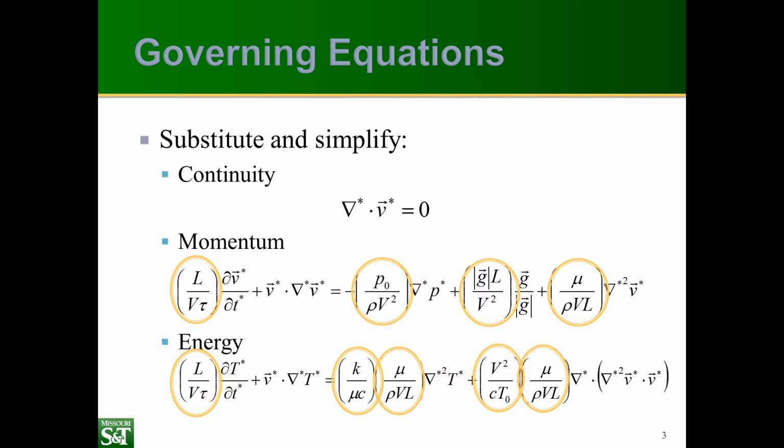Now, it's important to note that these are not the only dimensionless products that are important for fluid mechanics. If we consider compressible flows, we'll end up seeing Mach number and some additional dimensionless products. We can also look at boundary conditions and see dimensionless products that include surface tension or surface roughness and so on. The problem is that boundary conditions and so on are going to be specific to a particular problem. So we're not going to talk about them here. It's just important to be aware that additional dimensionless products exist relating these boundary conditions.